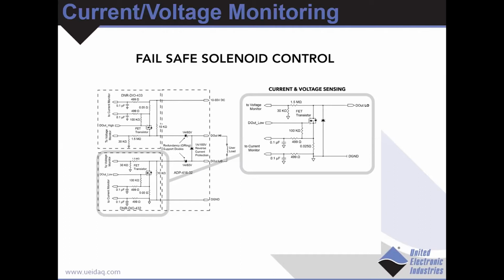So if we think of the voltage sensing, so we had one battery or both batteries that were shorted. Well, with voltage sensing, we could have detected that. So prior to this catastrophic failure, we could have identified that the battery was shorted. Now we know if we replace the battery, now we know that's working. But how do we know the solenoid is actually working?